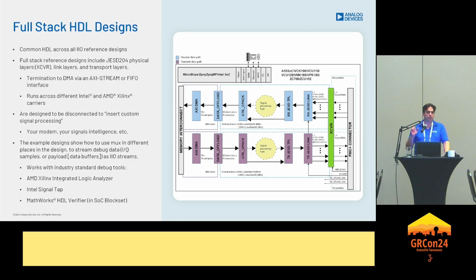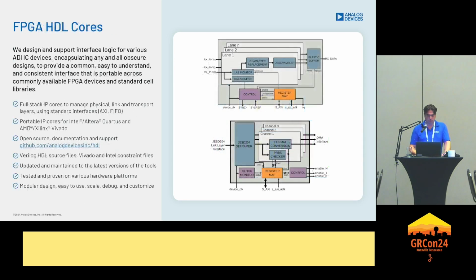You generate the processing logic and then you insert it into the design and you resynthesize it, build the bit stream, and then you can have potentially different bit streams that are being loaded for different configurations. We also support industry standard tools, AMD ILAs, Intel Signal Taps, MathWorks HDL Verifier, and so forth.